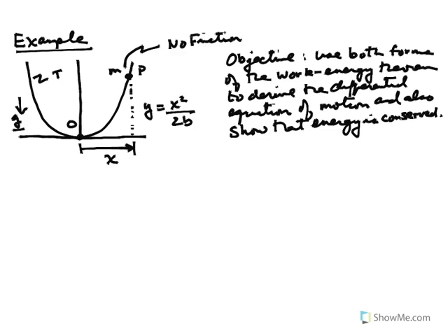So how do we go about doing this? It's done as follows. We're going to set up the kinematics, and then we're going to look at the kinetics, and we're going to apply the work-energy theorem. So for the kinematics in this problem, we only need to go up to velocity because we're dealing with energy. We don't have any acceleration in the results that were presented here. Because there's no rotation, we only have one reference frame. So that one reference frame is going to be the inertial frame.